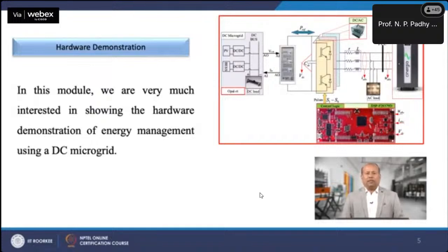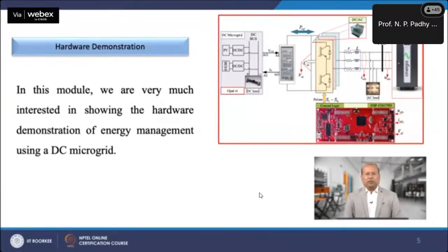After the configuration, the ADC pins must be configured to get physical signals into the DSP controller. Make sure that the ADC pin configured inside Simulink is the same as the pin the signal needs to connect to. The control system processes the signals and generates modulation signals, which are used to generate PWM signals. These PWM pins need to be configured to take out from the DSP board.